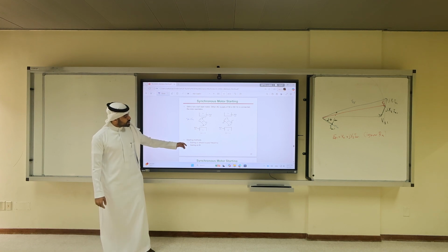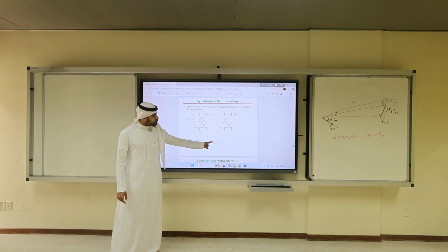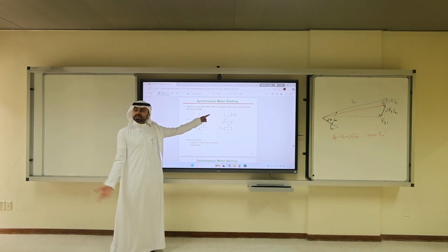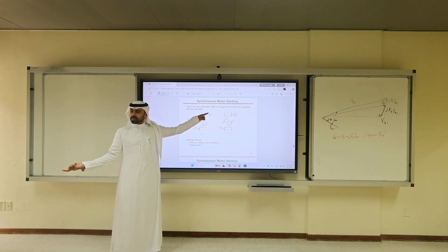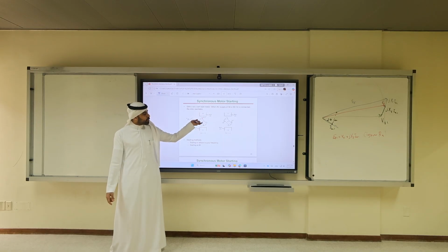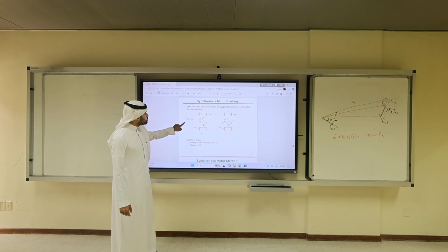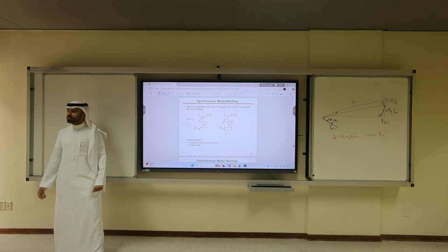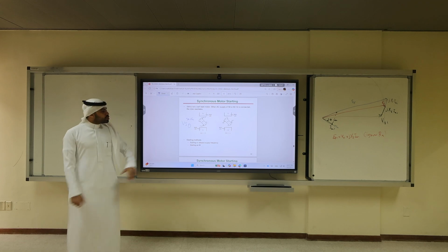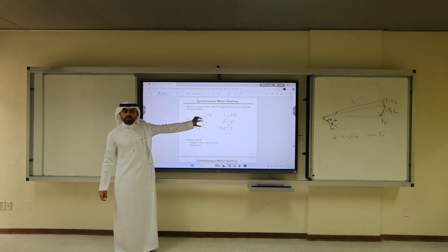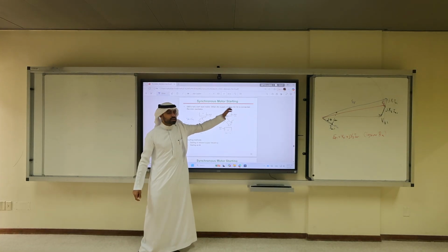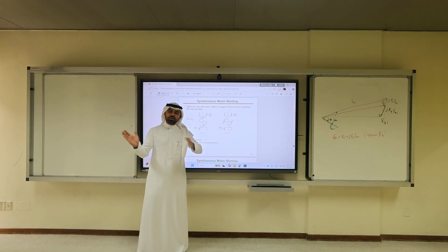So one of the two methods is starting at reduced supply frequency. Instead of 3600 RPM, you make it 600 RPM, 10 hertz. If you make it 10 hertz, then the rotor will catch up and be synchronized, and then you gradually increase the frequency. This job is achieved using variable speed drives, VSDs, power electronics. You remember VSD in the power electronics? You start at a low frequency. Which one, the rotor or the stator? The stator. Instead of 50 or 60 hertz, you start at 10 and increase it gradually so that the rotor would catch up.